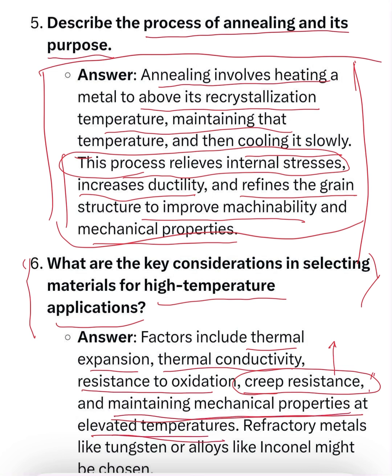If you are working on alloys like aluminum based alloys or magnesium alloys, they usually show very high mechanical properties at room temperature, but when you test these alloys at high temperature, let's suppose greater than 200 degrees Celsius, we are not able to retain the mechanical properties found at room temperature.